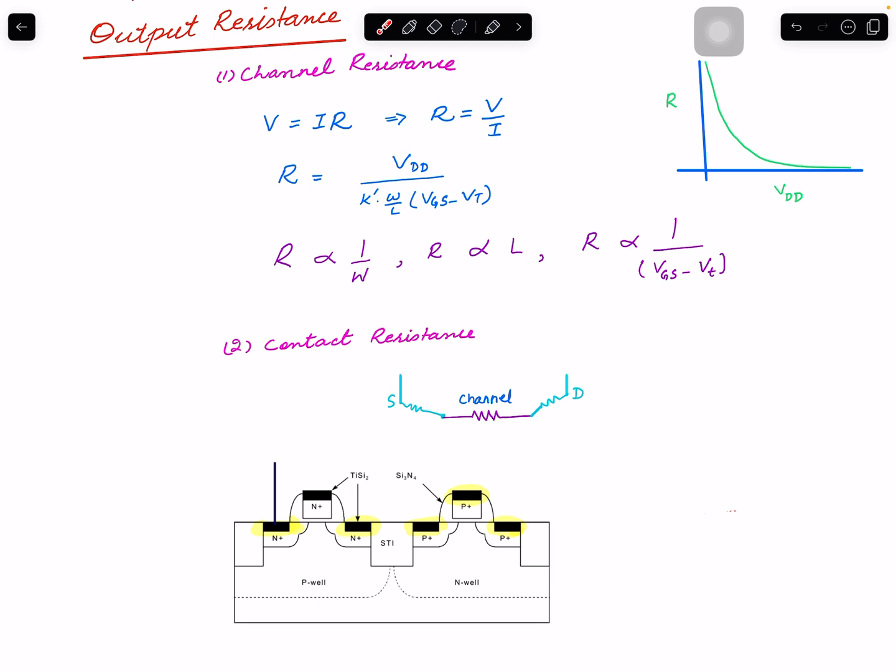They put this in because there is a resistance when you make a contact with the diffusion layer. Typically the wire in this 250 nanometer technology was aluminum, I think, so aluminum goes directly there. When aluminum goes directly into the N plus material, this barrier is very resistant.